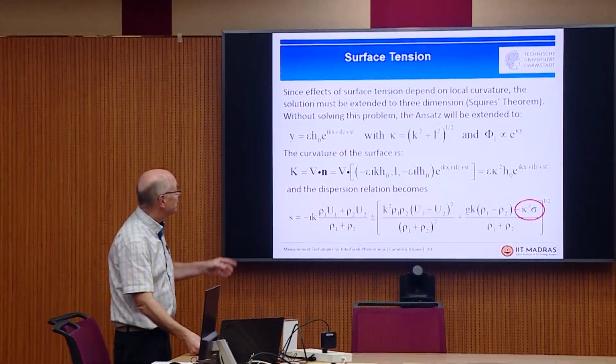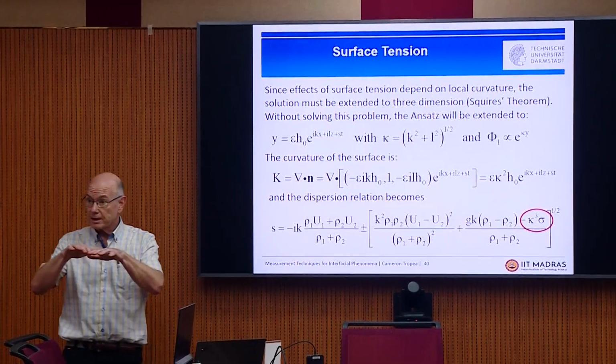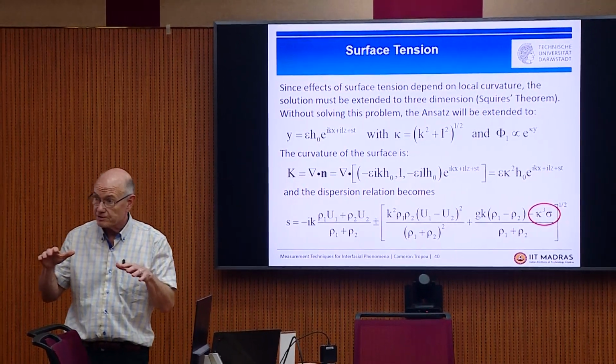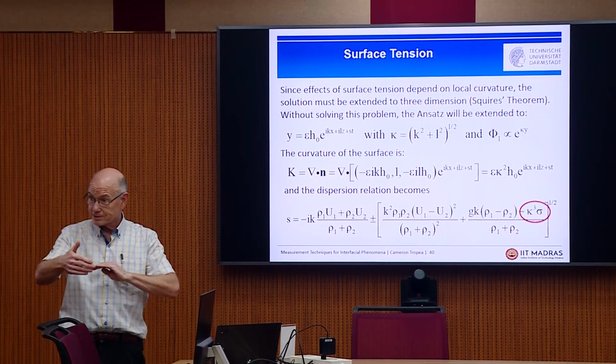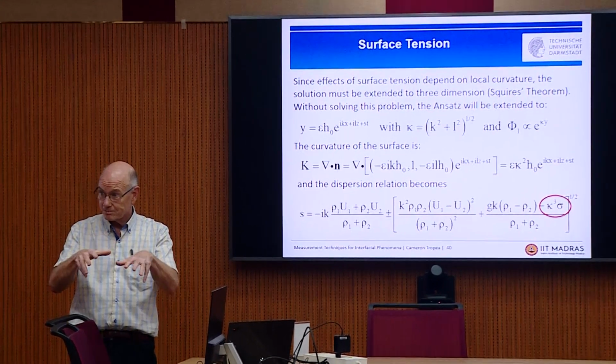If we now add the situation of surface tension, then we have to remember there are always two curvatures that give the pressure difference. Then we must go to 3 dimensions. You see, before I was working axisymmetric, only 2 dimensions, Z and R. I didn't worry about this dimension. But if we add surface tension, I need the 3rd dimension.